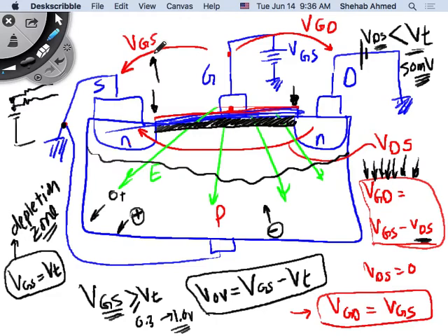Do we agree? If VGS has some overdrive, that is equal to the gate voltage minus VT. Now VGD is equal to VGS minus VDS. Do we want them to have the same overdrive? In certain cases, if the VT is small, yes. If VT is small, how would it affect? It will affect the characteristic. That's what we will see, but we're going to the whole characteristic now.